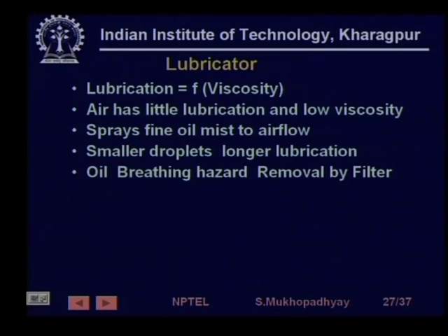You need not return the air, that is fine, but at the same time you cannot release the air just like that into the atmosphere because of that oil mist, because it is a health hazard. So before releasing into the atmosphere, this oil must be filtered.